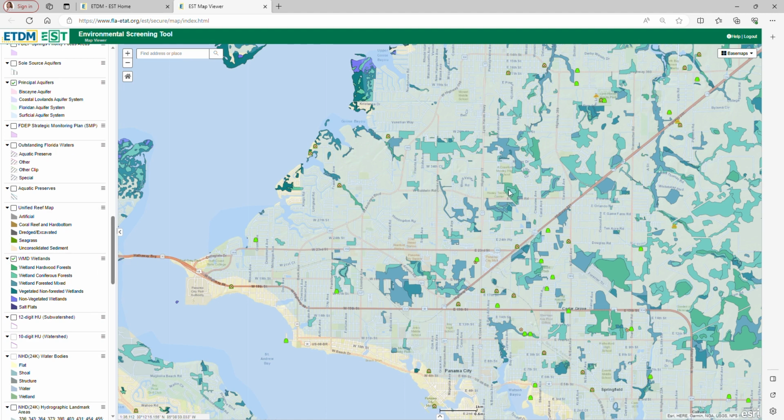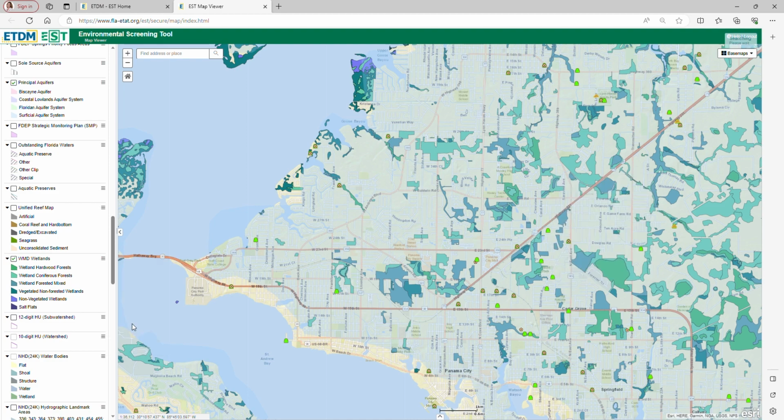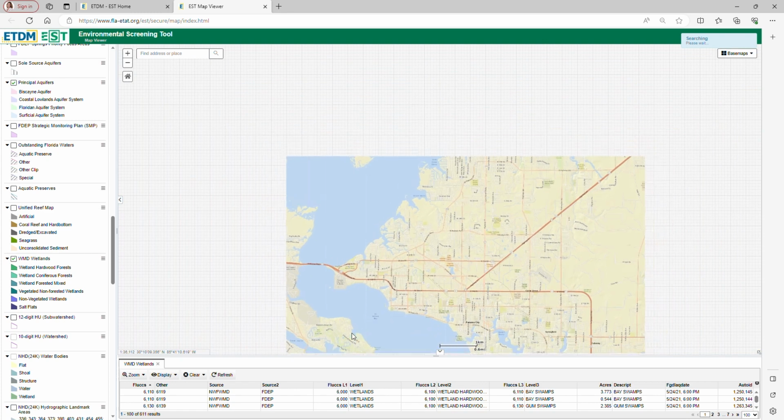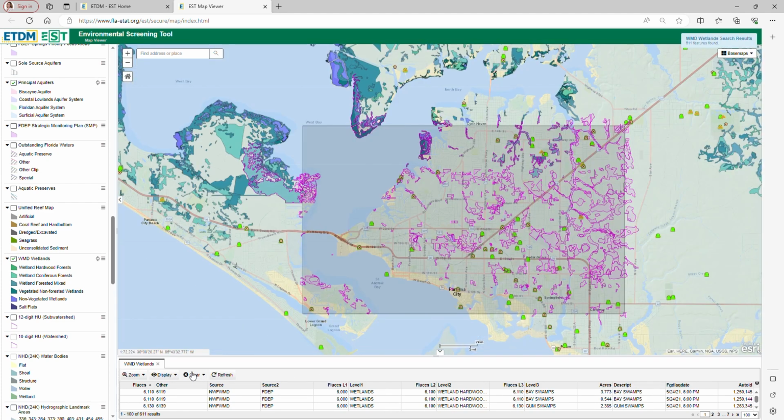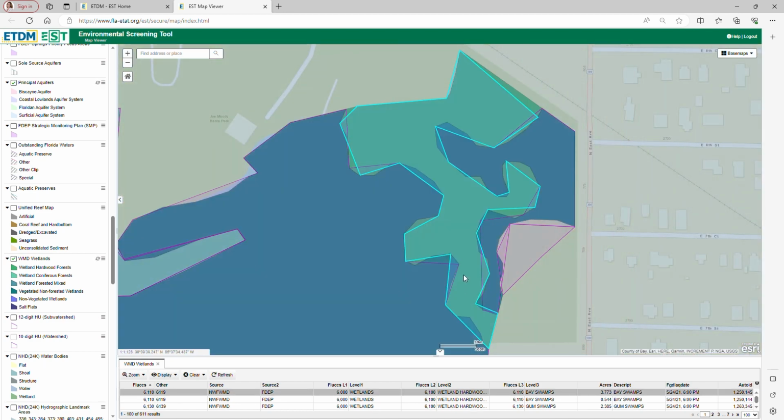So once you have everything you want to look at for the time being, you can then select on the actual layer, and it can give you more information on a specific area or a specific item that you are interested in. Another way of doing it is that you can go over to the data layer hamburger menu and select Open Attribute Table. That will probably zoom out on your area, but it will provide attributes for the one you selected. You can select each attribute in the table, and it will take you directly to that one. So it may zoom very close in, and again, you can always zoom out.